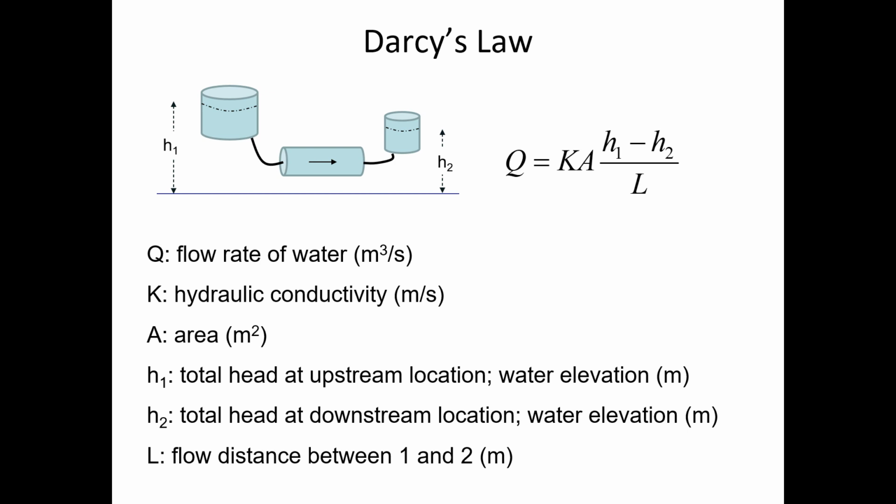So that's one of the things that we have to be familiar with to predict how quickly water moves through soil, is this idea that there is a parameter, K, the hydraulic conductivity, that describes how readily water moves through soil. And like I mentioned before, clay has a really low hydraulic conductivity. In fact, clay is so good at avoiding the transmission of water, I guess you could say it's bad at conveying water. They use compacted clay under landfills as a protective layer.